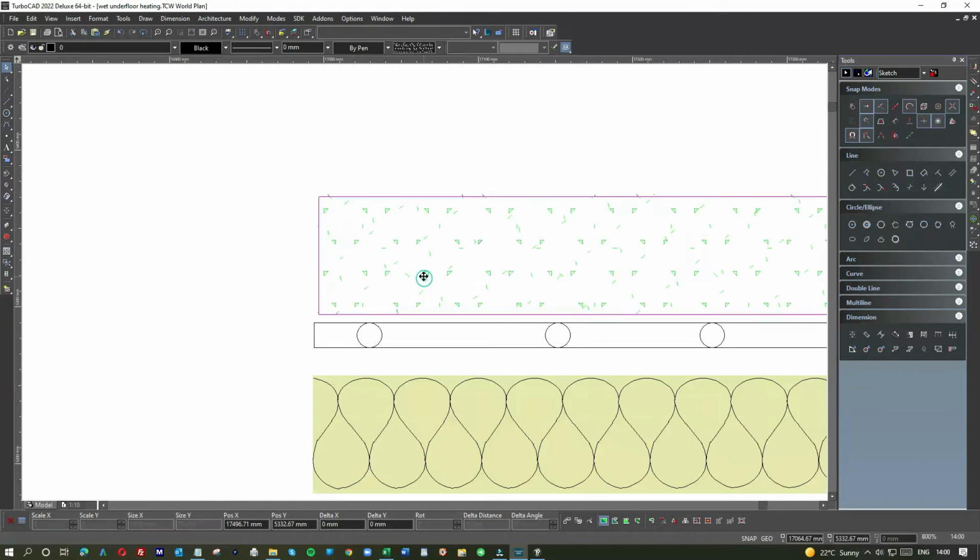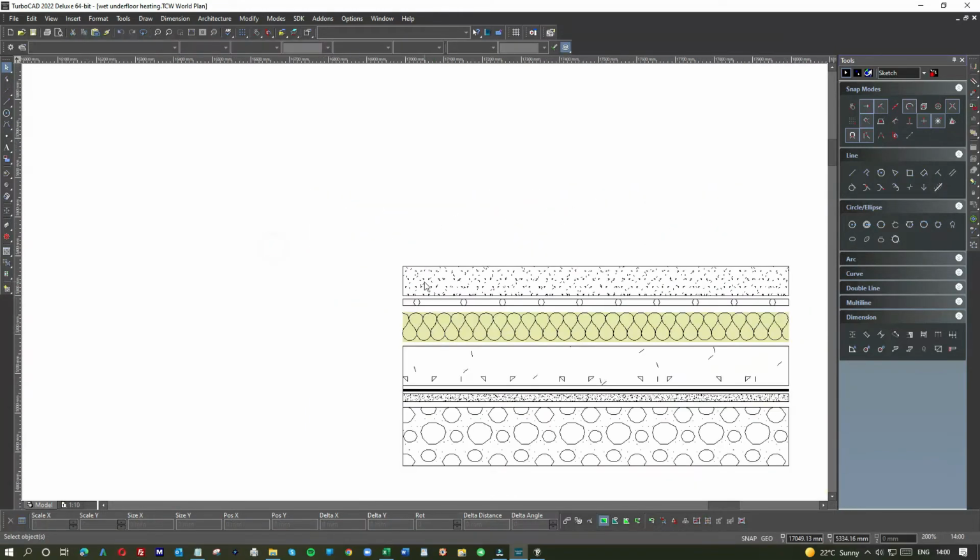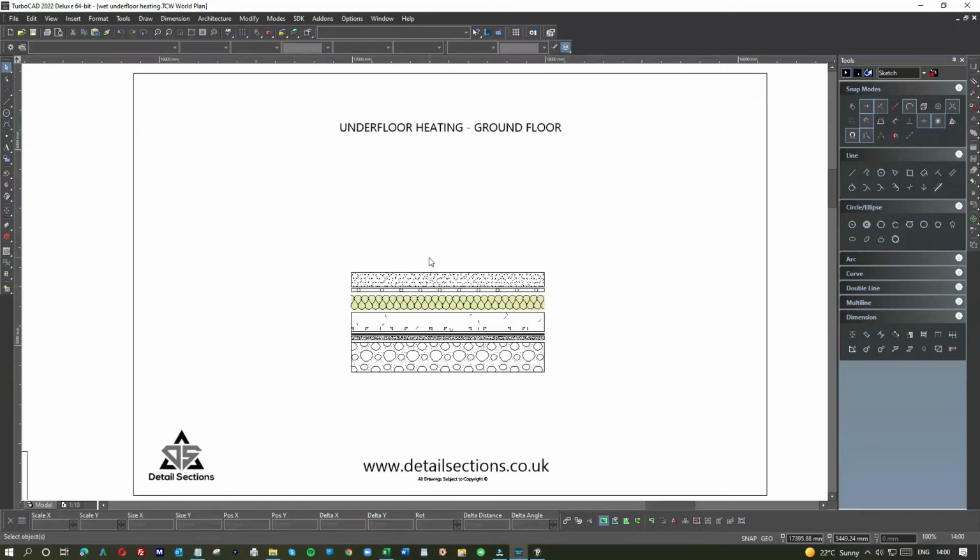Right, now the screed, 60, 50, 70, it depends on the specification of the installer, what they decide, because the reason it's specified is that to get different heat outputs in the room, you need different layouts for the pipes, and depending on the circumstances, there might be more than one zone within one concrete section. So if there's more than one zone, there'll be, say, one pipe coming in and going out for this half, and then another pipe going in and out. So everything is absolutely according to wherever the underfloor heating is being installed. So there's a unique specification for that.